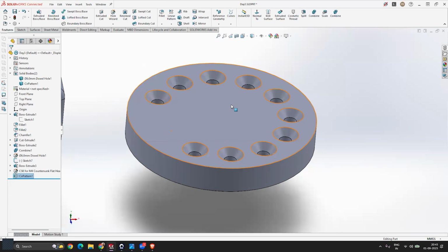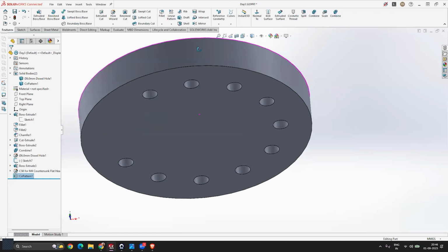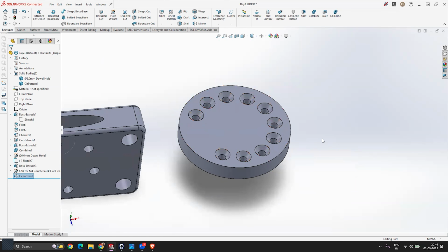And my recommendation is always, whenever you're creating any solid body and it needs a hole, then don't create the hole using the extrude cut operation. Always use this hole wizard tool to create a hole. And why I am saying this, I will explain in a detailed way in the drawing section. Once we start converting our models to drawings, you will have a clear idea why I am saying this. So whatever I am saying right now, just remember that. Here you can see this is what we created right now.